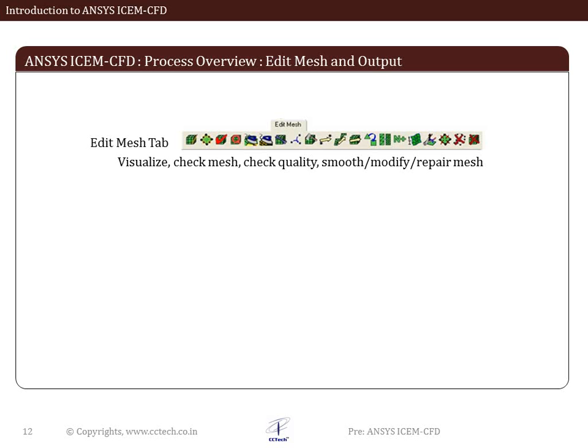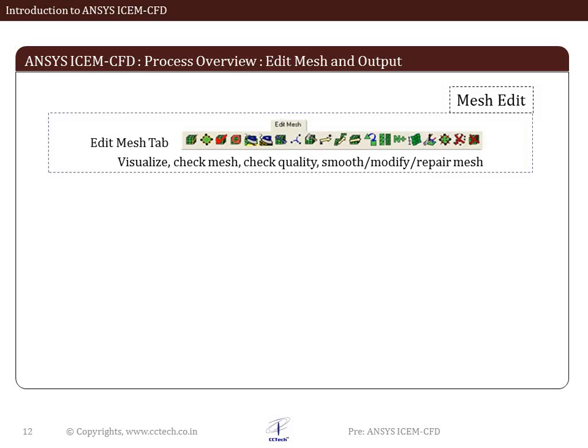In case the quality of the grid is not good, we can use various mesh edit tools available in ICEMCFD. A few of the tools are automatic and a few require manual work. Edit mesh tools are mainly used when unstructured grid generation methods are used. In case of multi-block structured meshing, the quality of the grid is mainly improved at the pre-processing level by modifying the block topology or vertex alignment. Edit Mesh also provides other tools like generating the conformal interface between two mesh domains, extruding the boundary mesh in a specified direction, transforming or aligning the mesh, and quality checks. So, overall mesh edit operations are used to improve the quality of a grid.